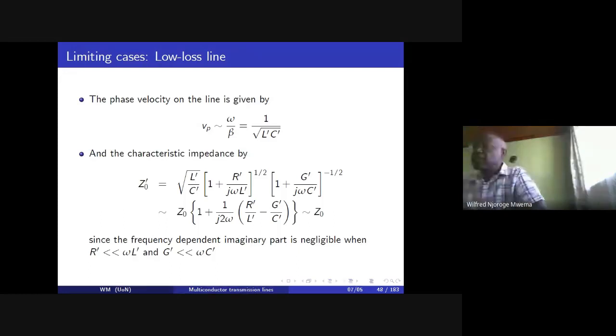So this is an exercise to just show you what would happen, and therefore I want you to expand that and retain the first three terms of each expression, and then get approximate expressions for the attenuation constant, the phase propagation constant beta, as well as the characteristic impedance. And you show that these now become functions of frequency, and when they become nonlinear functions of frequency, then we'll see that a lossy line is always going to be dispersive.